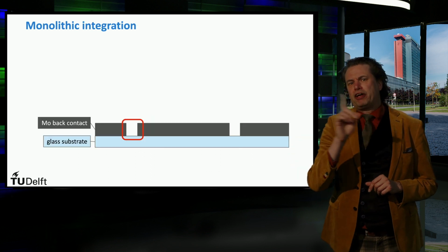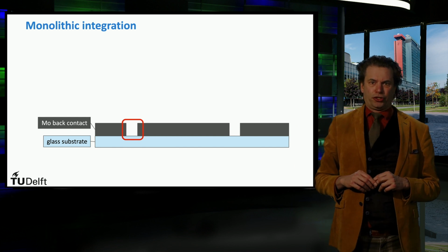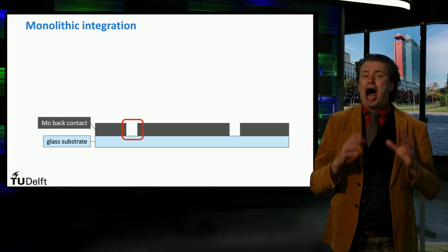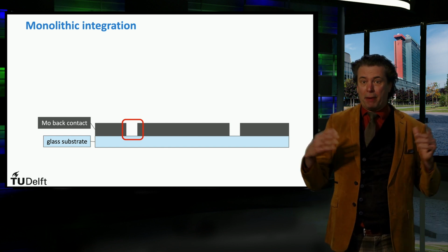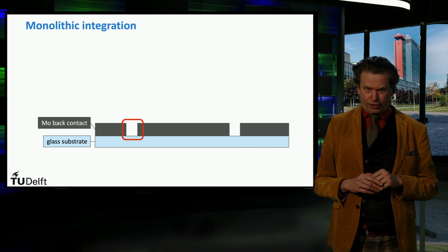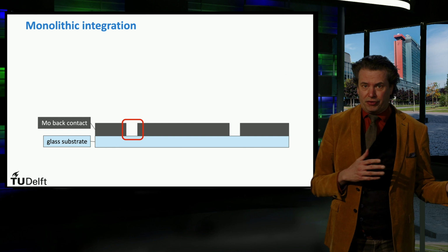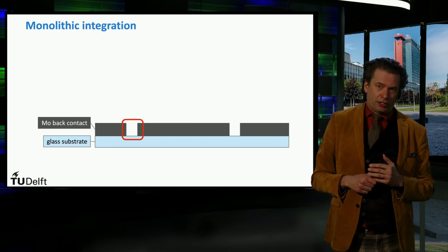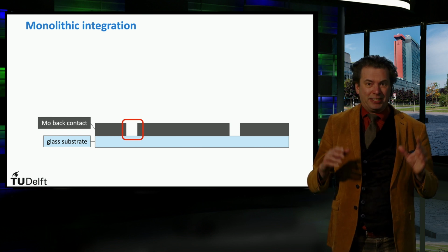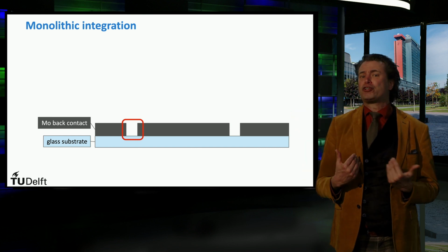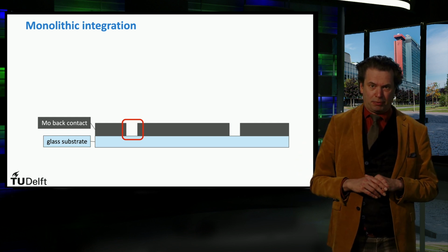We have discussed two different deposition approaches and discussed the traditional cell structure. Now we will show how cells are most commonly interconnected in thin film solar modules by means of monolithic integration. Usually, separate solar cells in lateral direction are made by scribing the layers, most often by using an absorbing laser. The molybdenum back contact receives the first laser scribe prior to the CIGS deposition step.